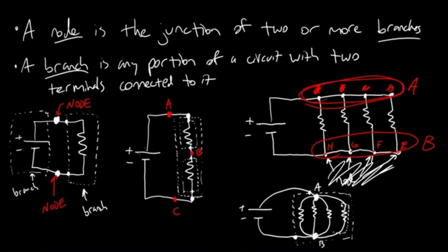And you can still treat each individual resistor as a branch. But again, those nodes are not actually separate things. So if I look at these two resistors and say, okay, well, this one has a connection there and this one has a connection there, again, those are electrically equivalent because they're just directly connected by zero resistance wires. So be careful. Don't get tripped up when people start applying Kirchhoff's current law, which we're going to see in the next video. People can get tripped up in circuits like this and start trying to apply that to each junction here, where you look at the currents flowing in and out of each one of these lines at each one of these intersections, and that becomes redundant. What you really want to do is look at it like this, where you're only analyzing that single node.